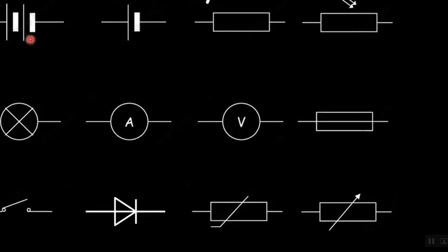The first one over here is typically what we would call a battery. Okay, a battery is not what we typically would call it today. It is any combination of one or more cells. So this is a cell. When I only have one of those, it's a cell. When I put them together, it forms a battery. A car battery has 6 individual cells that form a battery. But a normal battery that we call a battery is actually simply a cell.